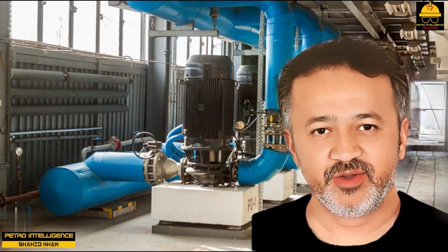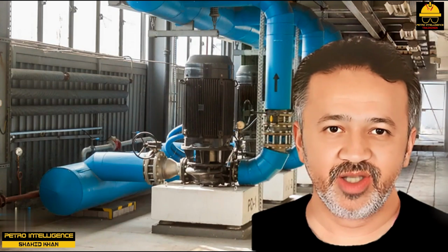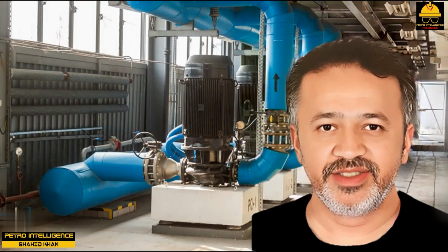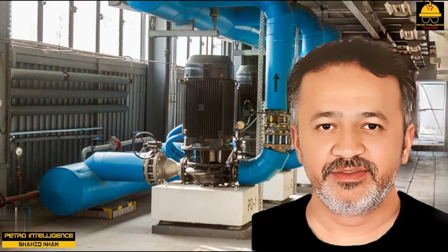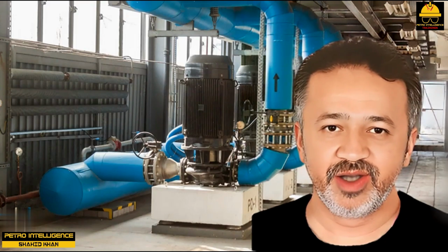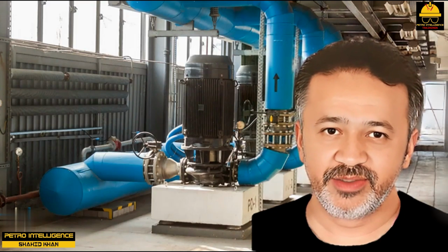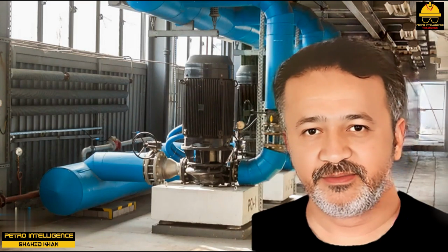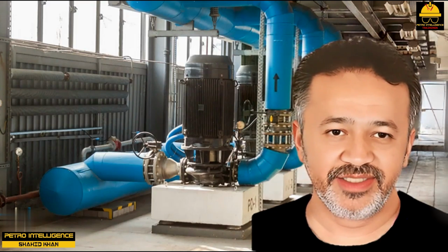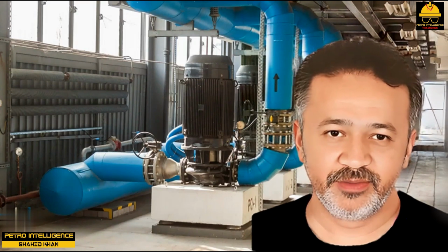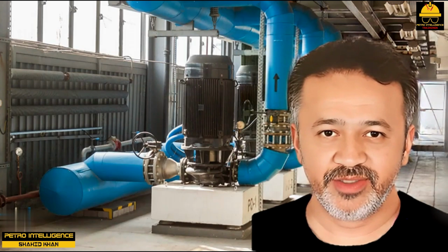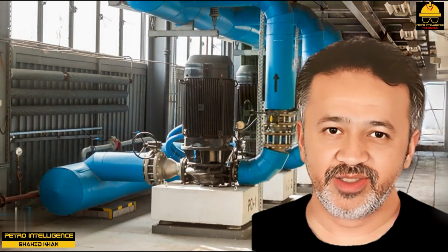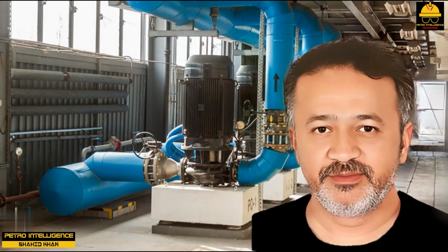Increasing the size of the impeller by 10% will increase the amperage load on the motor driver by 30%. For many process pumps, this would require a new motor and breaker to support the larger impeller. Trimming the pump impeller on a lathe also requires the reshaping of the tips of the impeller vanes. Most often, this requirement is ignored, and the revamped pump operates below its expected curve. Rather than worry about these fine points, it is best to order new impellers directly from the manufacturer.